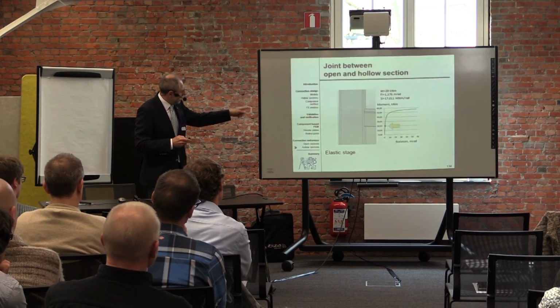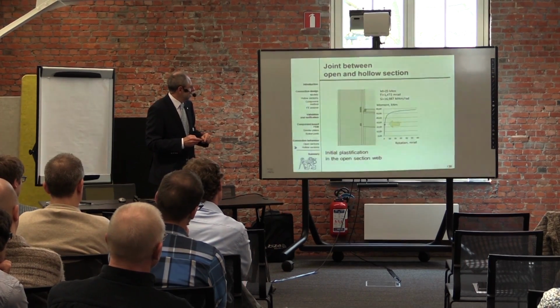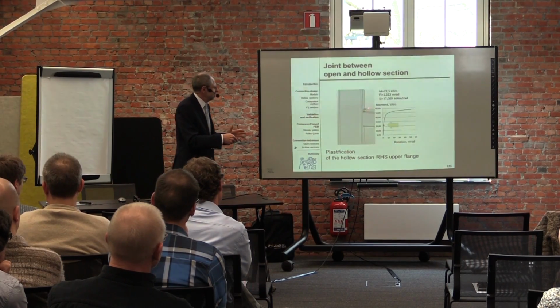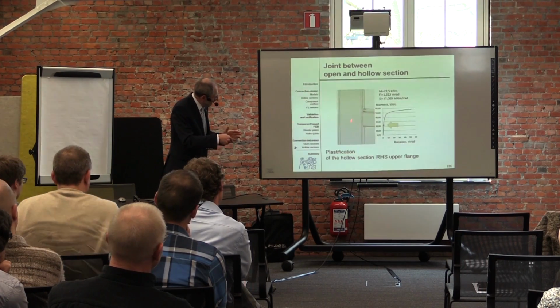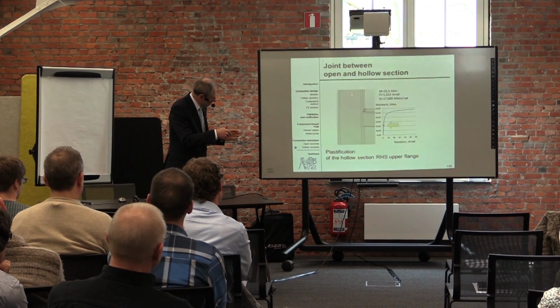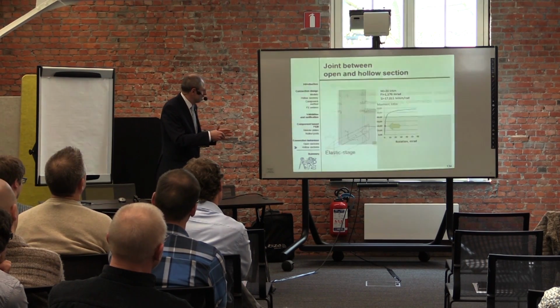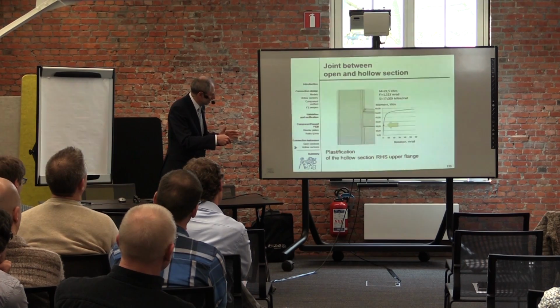So here I also have global behavior. Here you see where the plastification starts. It is the connection between an open section and a hollow section, a rectangular hollow section.